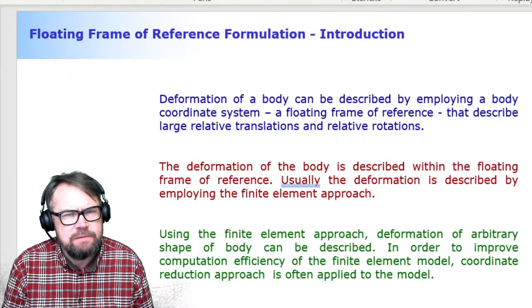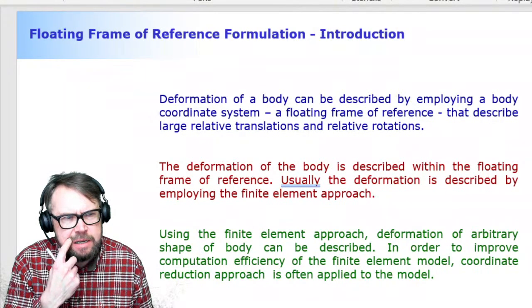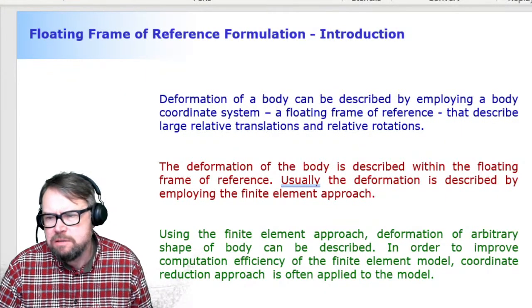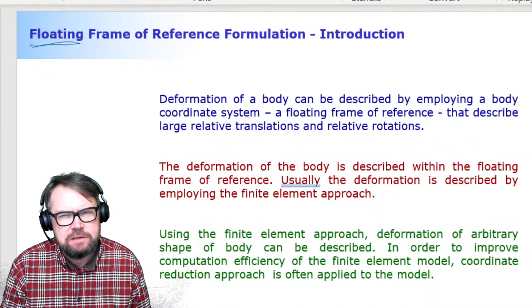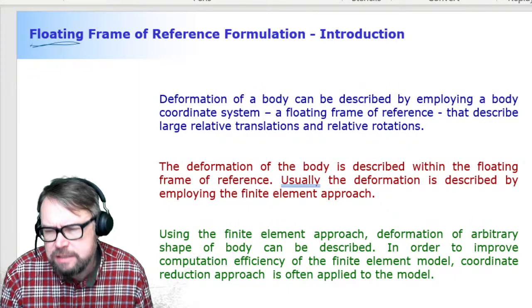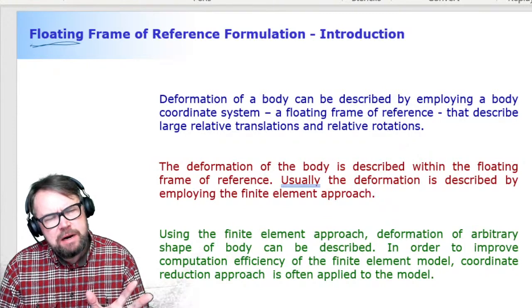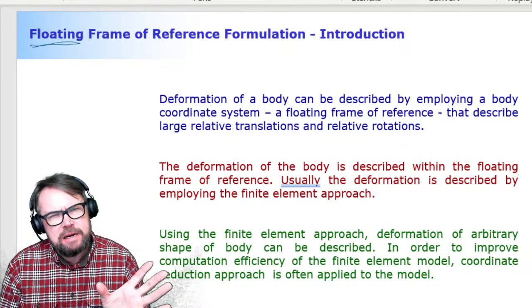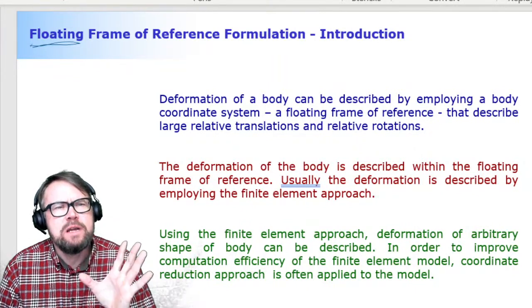So a few observations. The core concept in the floating frame reference formulation is that you're describing your deformation with respect to the body reference coordinate system. And like the title floating implies, the body reference coordinate system is kind of traveling with the body, kind of rotating with the body, but not rigidly. It is traveling in a floating manner.